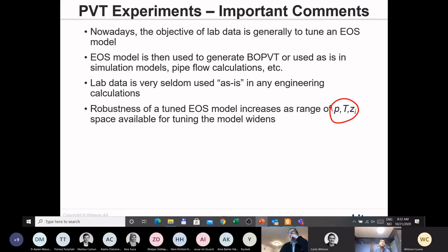And that's something we discussed when we were discussing the reservoir representative samples and in situ samples. That's the whole idea behind using any reservoir representative sample in tuning your EOS model. Because any reservoir representative sample originated from your reservoir fluid, that composition and any PVT data on those samples should and always be used in the tuning of the EOS model.